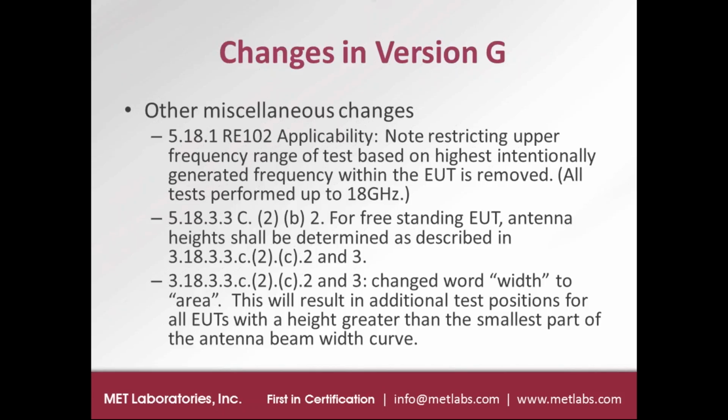One, prior to version G, the upper frequency range of measurement of RE102 was determined based on the highest frequency of the EUT. And testing up to 18 gigahertz wasn't required for all EUT. However, that restriction is removed, and now all tests are performed up to 18 gigahertz. The other change is that